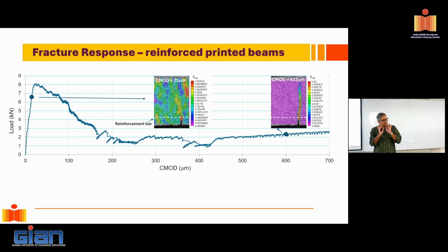And remember, this is a plain, smooth wire, so there are actually no ribs or anything helping with the anchorage, and it's simply dumped there. So we printed 1 layer, put a steel layer. For that itself, we are getting some residual load carrying capacity from this wire that is placed there. And this basically replicates what I do with the template. Remember that we are printing 8 layers, putting a steel template, which basically had the same centerline shape as what I would get with the filaments.